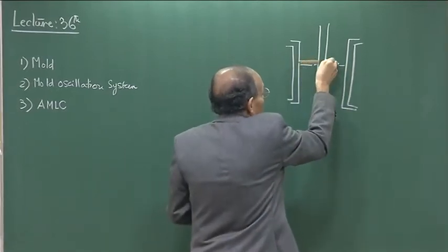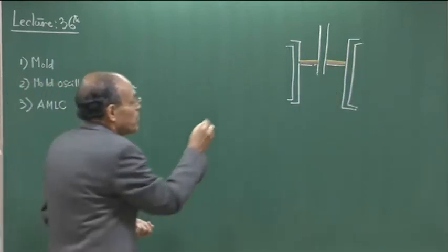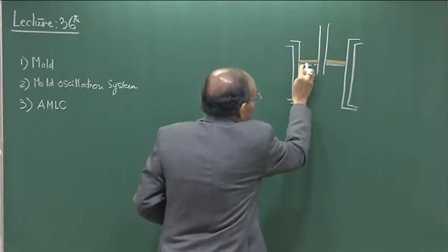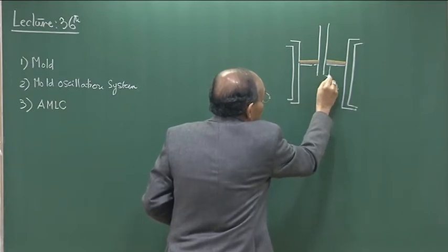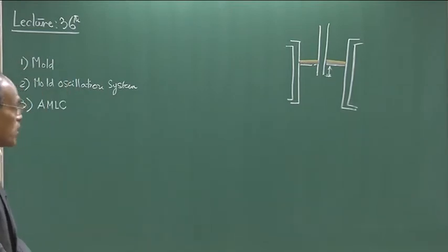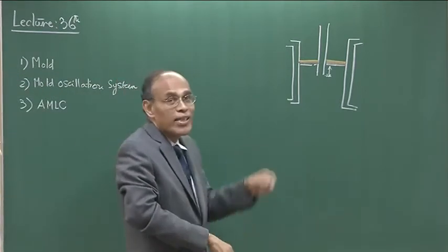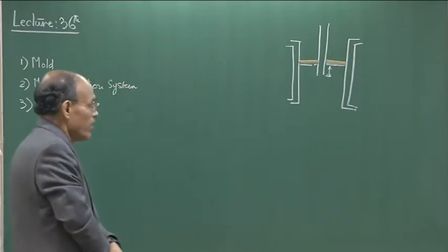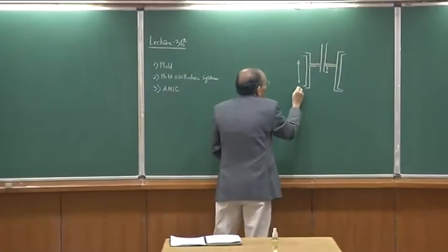If the mold level, meaning the level of the liquid meniscus, fluctuates, then the distance of separation between these also changes dynamically, and this is a very important parameter in continuous casting of steel. Therefore, there are measuring equipment, sensors available, which tell us to what extent the meniscus level is actually fluctuating, even though the mold may be doing up and down movement.